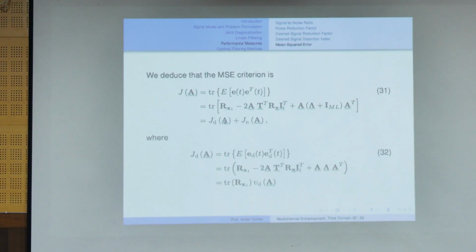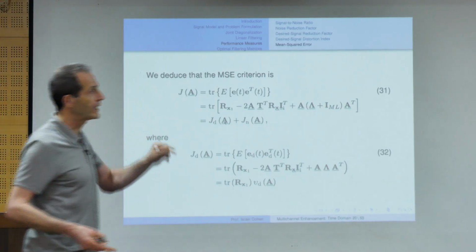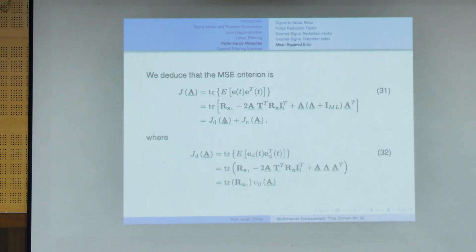So you see, even here, when you formulate the problem, already we understand 3 different types of filtering matrices. One filtering matrix is MVDR, which is simple. In the transform domain, we keep the projection in the first P eigenvectors. We take the measurement y, this vector, and we keep the components in the signal subspace that is spanned by the first P eigenvectors, and we suppress the noise-only subspace.